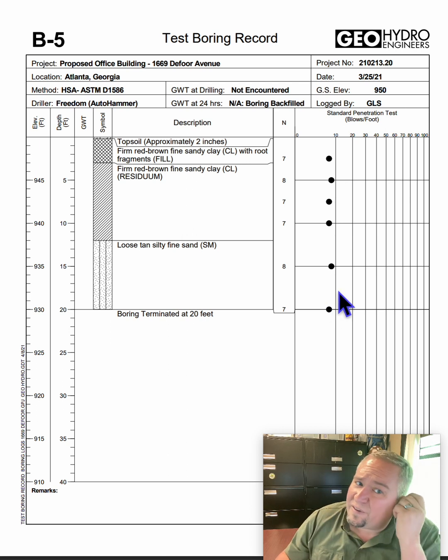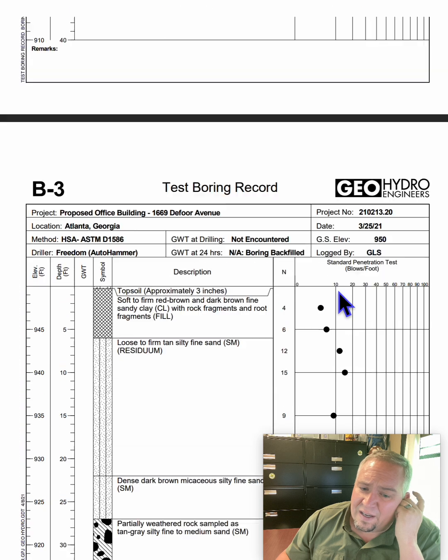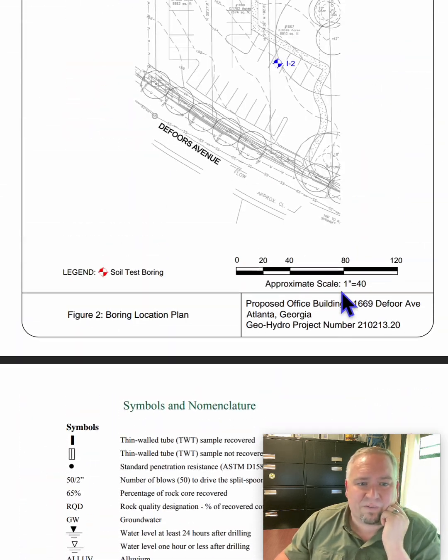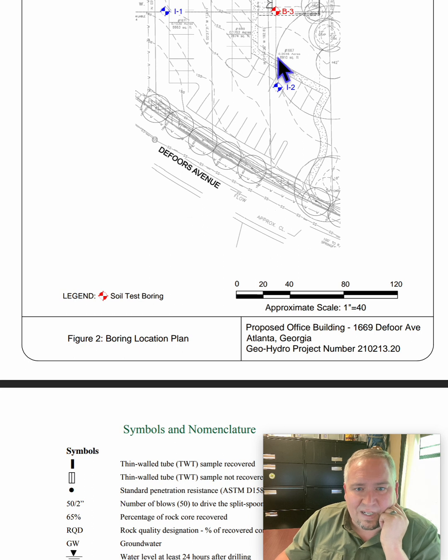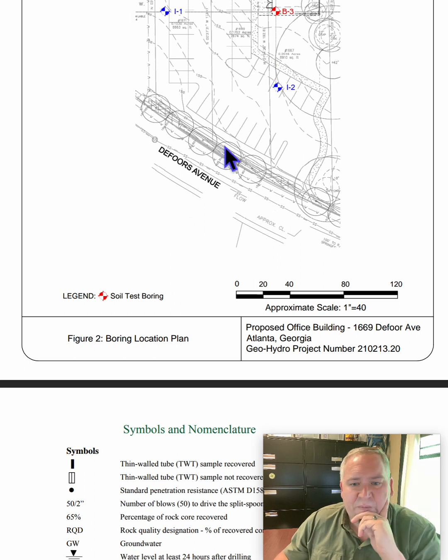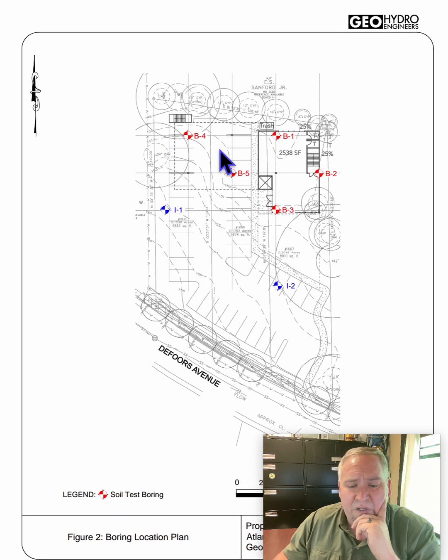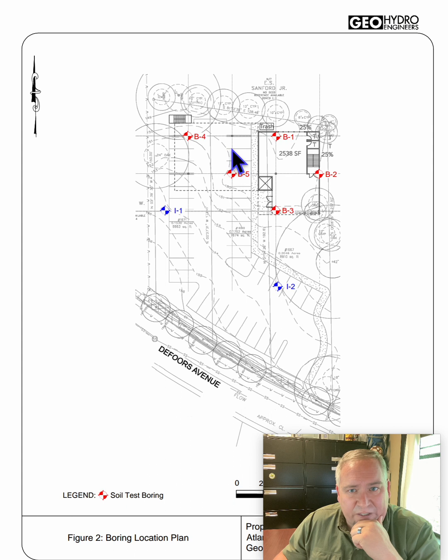So there it goes down to B5. Again, I didn't see the confirmation, so I would be sending the geotech an RFI, request for information, on what these blue icons are here. I could probably spend some more time digging into this and find it, but I feel like we've given it a good college try. I would just send them an RFI or give them a phone call. I need to introduce myself anyway if we've got the project, and find out what the details are here.